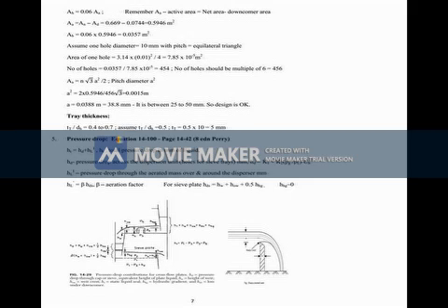You can see that at the top of the tower, the gas is lean and the liquid is pure, so it will be near the origin. That is why 0 and 0.00128. Join AB. From the graph, we get x1 equal to 0.035 and y1 is already known, 0.06. Find the slope. The slope is coming to 1.668. This is the slope of the operating line corresponding to minimum LS by GS.